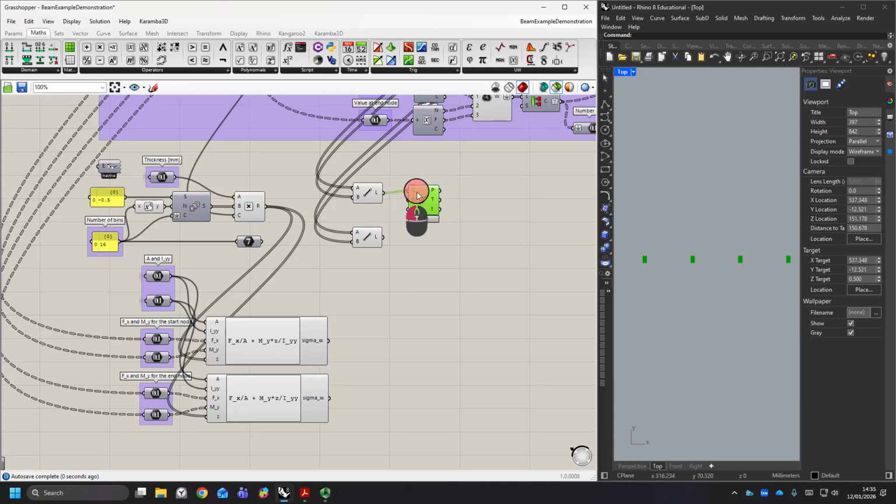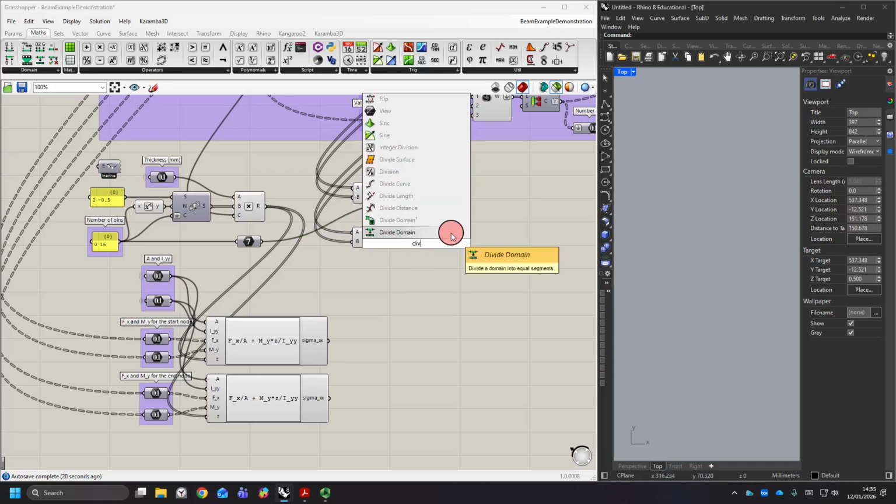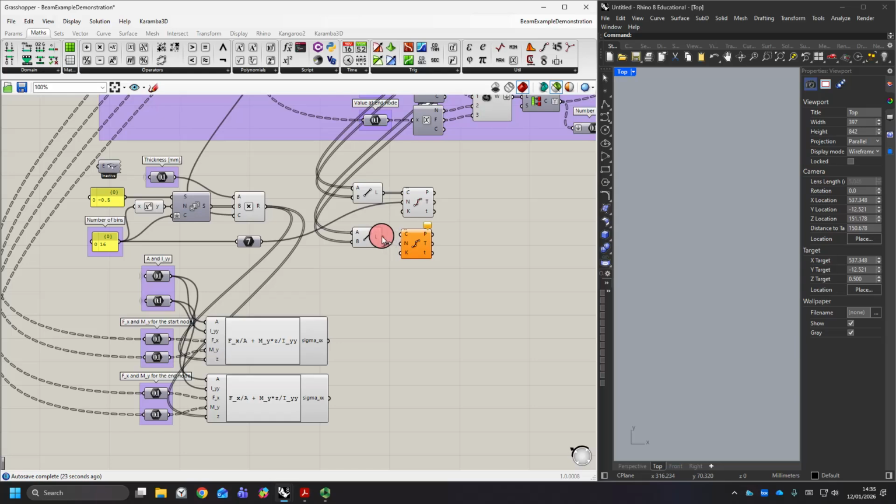So this is just another way of achieving something quite similar. So I can run my line in here, and then actually I am going to run the number of quadrilaterals or number of bins into here. So that then gives me a total of 17 points coming out of there, and those are the points that we're interested in, and we'll just arrange the data in a minute or so to do what we want. So we're going to do the same for the next one, so for all of the end lines, if you like, and again just taking that component from there.